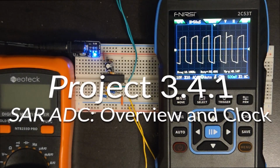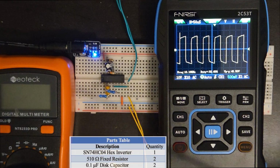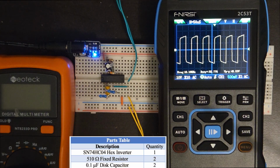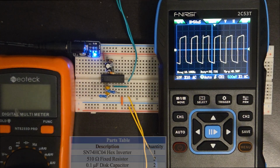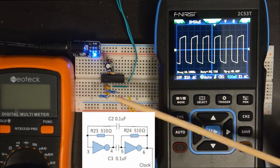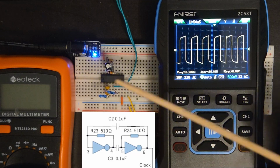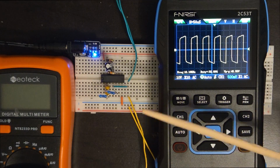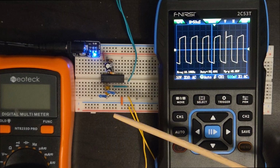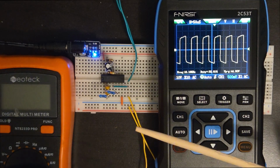Project 3.4.1, SAR ADC Overview and Clock. This here is the clock circuit of the SAR ADC, or the Successive Approximation Register Analog to Digital Converter. This clock circuit is made up of two resistors here and two capacitors, along with this inverter chip. There's two inverter gates used in this circuit, and it has a frequency of 10 kilohertz and a period of roughly 100 microseconds.